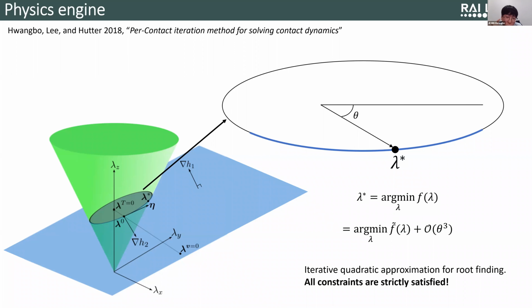But actually, we realized that for programming, this is quite bad because there is probably a bit of branching and so on. So this actually takes even longer than the numerical solution. So here what we do is we do iterative quadratic approximation to the criteria, and we converge to the optimum. This idea is, of course, similar to Newton's method, but it's not exactly Newton's method, the way we implemented it to make it more numerically efficient. I'm preparing a publication on this, so you can probably read more there. But anyway, this method is there in Raisim.